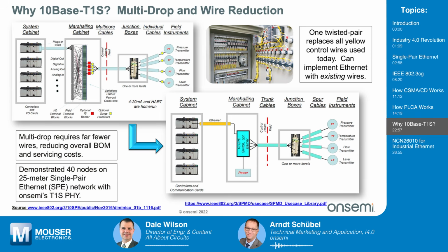If you think of cabinets, in-cabinet wiring, like we show on this picture here, where you can have motor starters, contactors, relays, whatever. On a typical cabinet, on the front door, you have gauges, you have push buttons, so-called pilot devices. And if you look at this particular picture, you see the amount of wiring that goes into a cabinet like this. And now this is also called the marshalling cabinet that basically makes a connection between all of these devices inside the cabinet. Now think of the installation process itself. A trained technician would roundabout take 6 minutes to pull one of these wires. Like figure the situation where you have to repair this cabinet.